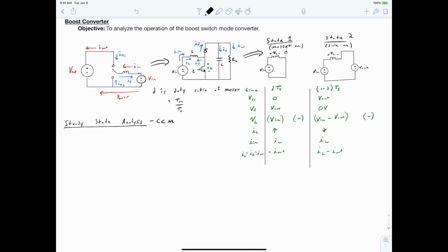Well, in a couple of lectures, we're going to talk about discontinuous conduction mode, where we allow our inductor current to go to 0. So for now, just keep in mind that the analysis that we've been considering so far pertains to the case where we have sufficient stiffness for our pole current. That is, our inductor current does not go to 0. Note that the input voltage of the converter is equal to the average pole voltage of the converter. You can see this by inspecting the single pole double throw converter diagram that we drew at the beginning.